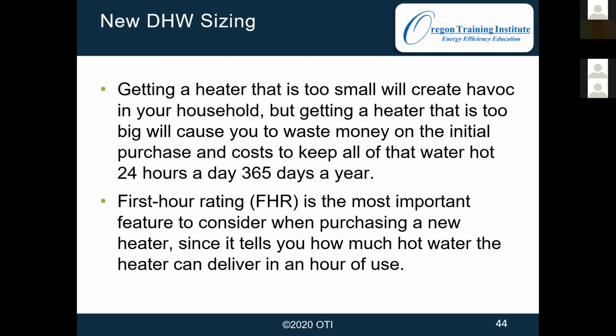If we do replace the water heater, we want to make sure the replacement is sized properly. And the way to size a water heater is not solely on the tank capacity. It's by the first hour rating is how you size a water heater. And you want to select a water heater that meets the needs of the home. So the first hour rating is basically how many gallons of hot water can it put out. And we're going to have to figure out our need to make sure we can meet it.